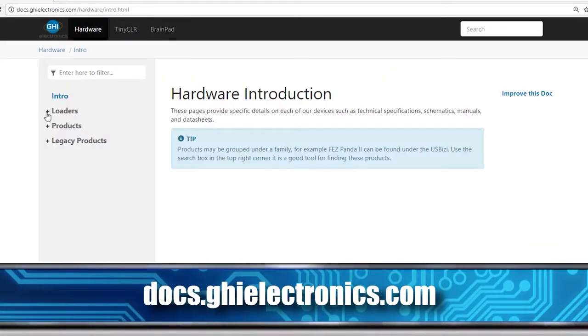Now, we need to load the binary file on any ST chip through DFU. You need to convert the binary to a DFU file. The first step is the same steps we always follow. This is explained in our documentation under the STM32 bootloader. So if you want to see the instructions there, I'm going to do it really quick over here.